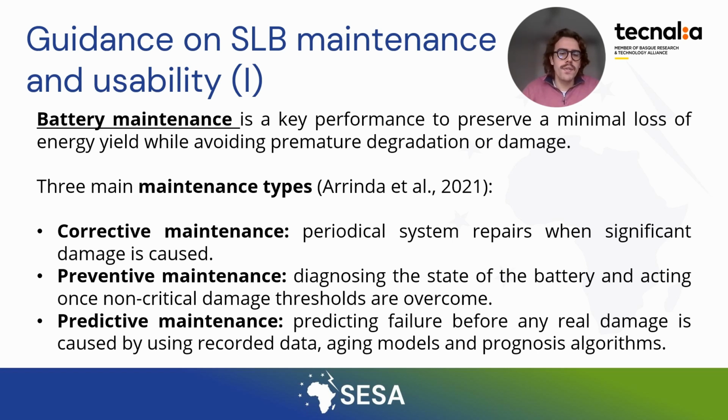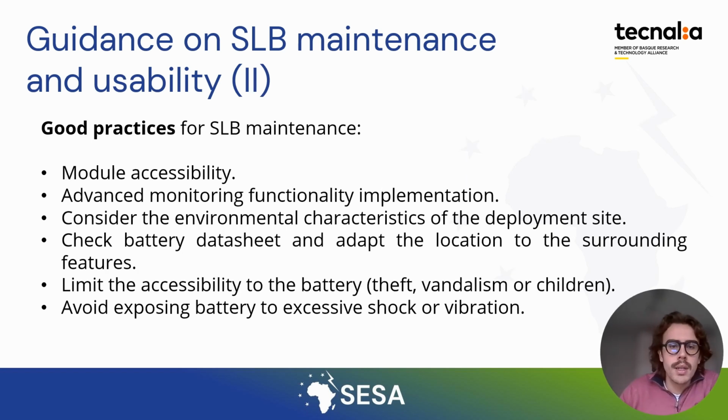And lastly, we have the most advanced maintenance type, which is predictive maintenance, based on predicting failure before any damage can happen to the battery by using historical data of the battery management system and aging models and prognosis algorithms. This is a piece of advice on second life battery maintenance and usability.